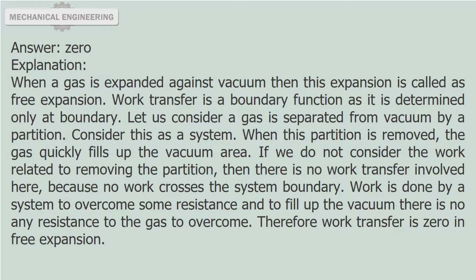Work transfer is a boundary function as it is determined only at the boundary. Let us consider a gas separated from vacuum by a partition. Consider this as a system. When this partition is removed, the gas quickly fills up the vacuum area. If we do not consider the work related to removing the partition, then there is no work transfer involved here, because no work crosses the system boundary. Work is done by a system to overcome some resistance, and to fill up the vacuum there is no resistance for the gas to overcome. Therefore, work transfer is 0 in free expansion.